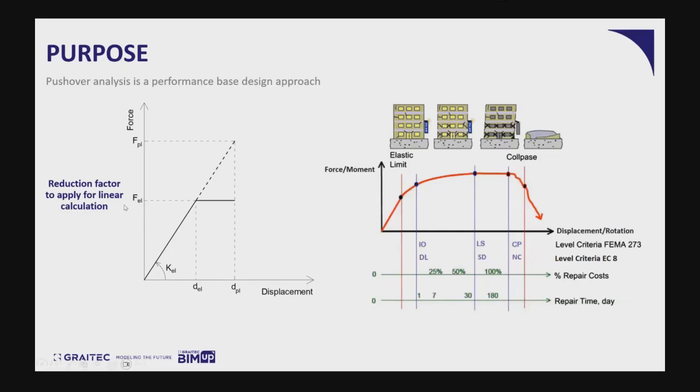The problem with this approach is that the reduction factor, also known as behavior coefficient, is defined by the codes according to the type of structures, and generally this factor is the same for the entire structure, which does not reflect the true case. In reality, each structural member will have its own reduction coefficient. So, this is what was previously called strength-based design.